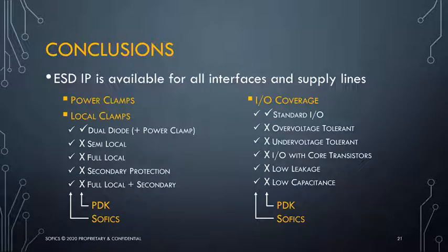A final overview: the solutions that are offered and are in existence for FinFETs and FDSOI include power clamps and local clamps. But in addition to the PDKs that also include the dual diode and power clamp solution, the Sofics portfolio offers you solutions for semi-local and full local protection, for secondary protection or full local protection plus the secondary protection.